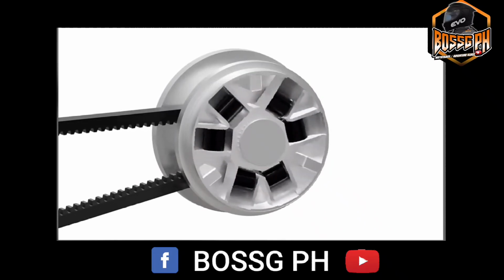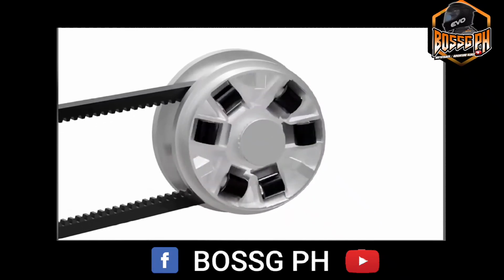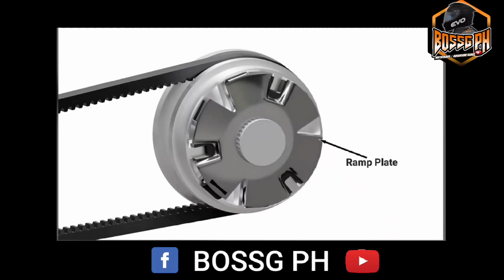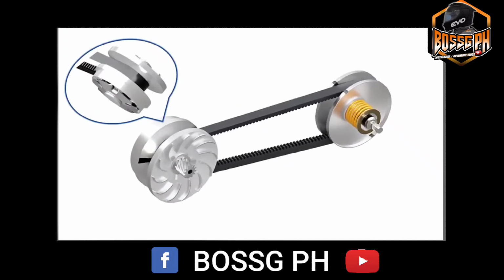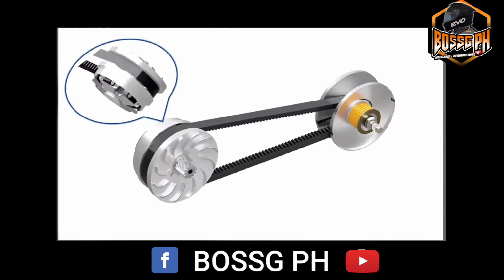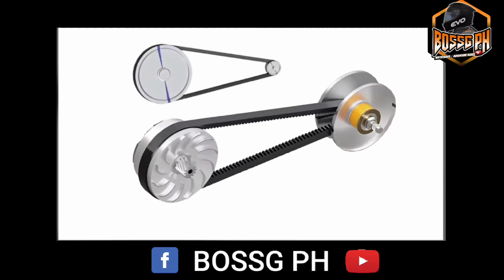As the engine gains speed, centrifugal force causes rollers to move outwards along a curved surface. These rollers push against the ramp plate. Since the ramp plate is fixed, the sliding conical plate is forced towards the other plate. Let's see the diameter change in slow motion. This is similar to the condition of high RPM, low torque as we observed in the demonstration.